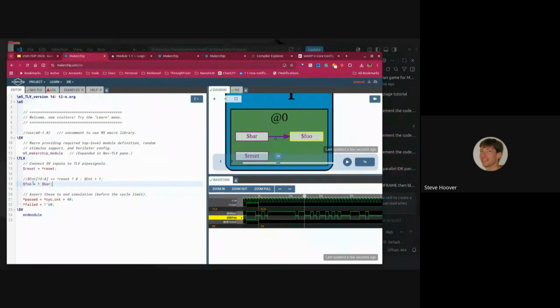With traditional EDA tools, you might spend a week just getting the software installed, getting all the licenses sorted out, getting platform issues sorted out to get to the point where the students are able to run a simple circuit, teaching the basics of Verilog, teaching the students about test benches so they can drive the stimulus to their circuit. You notice here we didn't do any test bench. We just coded a logic gate. The test bench kind of comes for free in Makerchip, in a quick and dirty test bench.